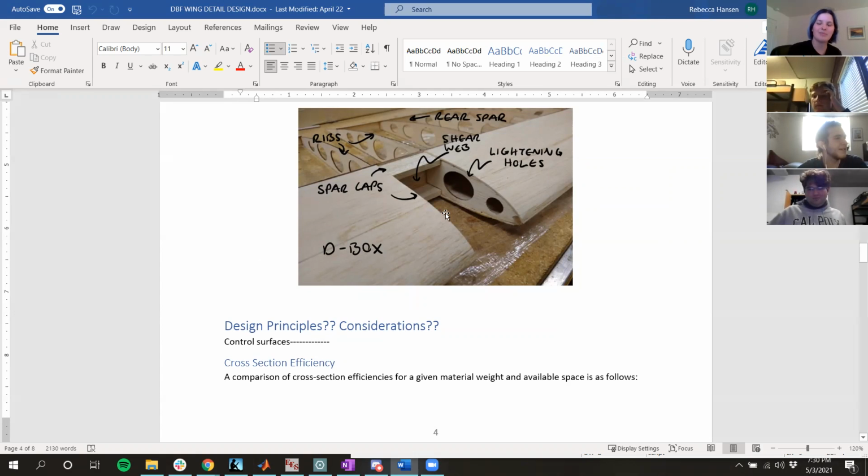Sure. Yeah, so you definitely want a really clean leading edge. So you're right about that. And you don't want any flimsiness or fluttering or warping in your plastic wrap on the leading edge, because that's critical for defining the boundary layer and everything, like following where it touches, and if you trip it to turbulent right away, then you're going to be turbulent and good fluids, stuff like that.